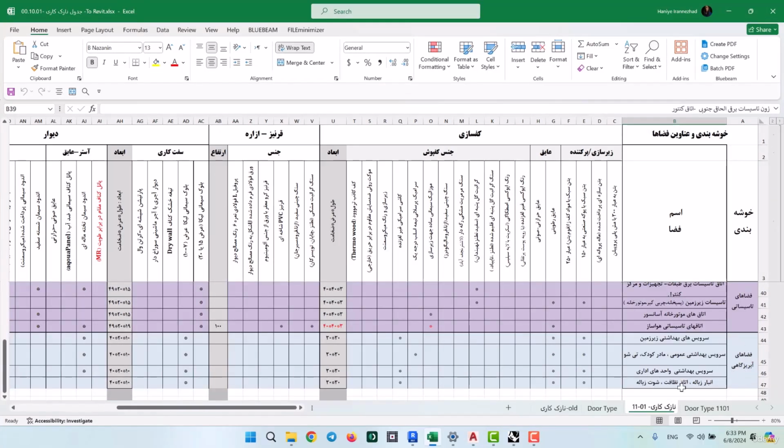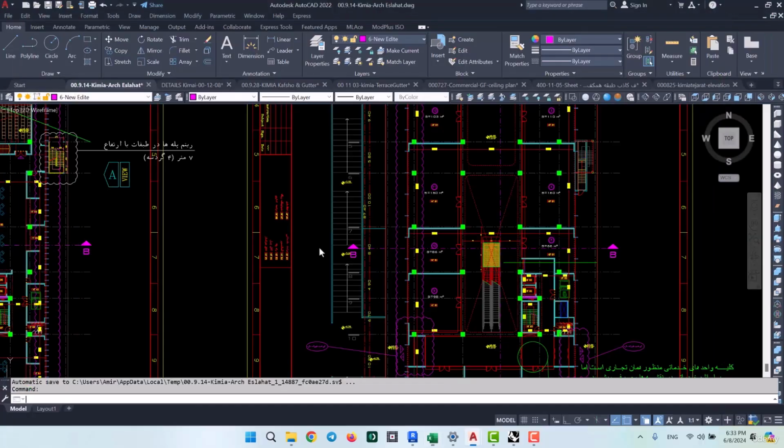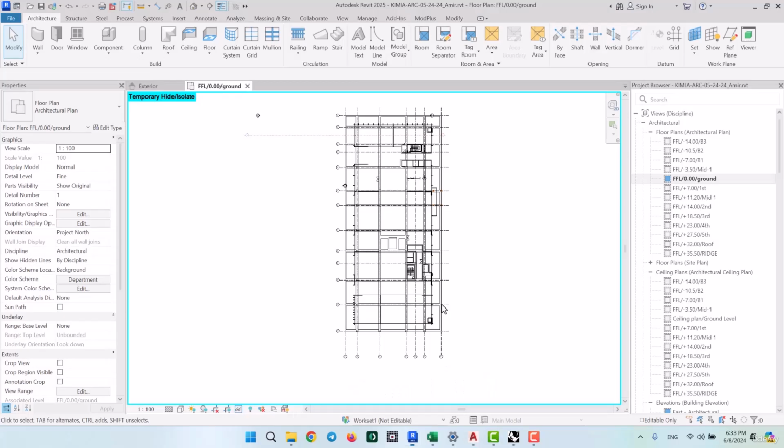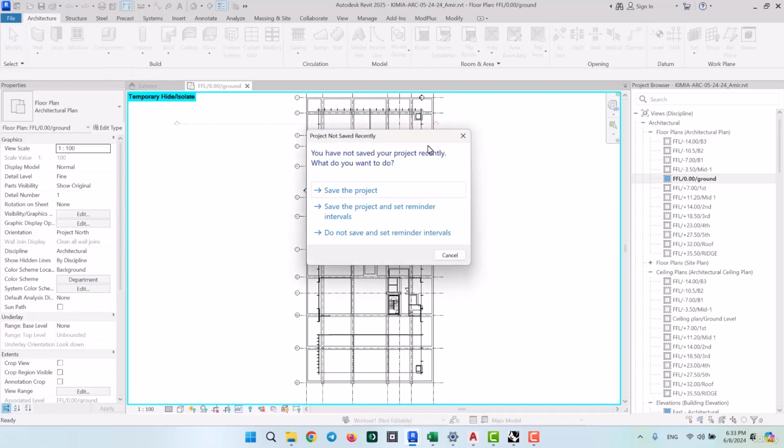for example, in the water discharge areas, here we can see the garbage storage, cleaning room and garbage chute, the floor of which needs to be non-slippery ceramic tiles, 30 by 30. So you can also figure out the information about the flooring of these areas further down. Now first let's go to the floorings of the non-mechanical and non-watery areas and draw them first.